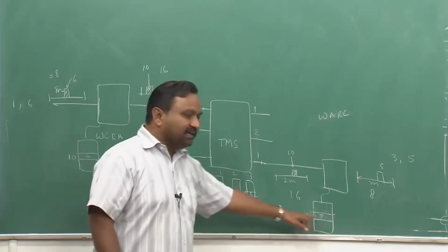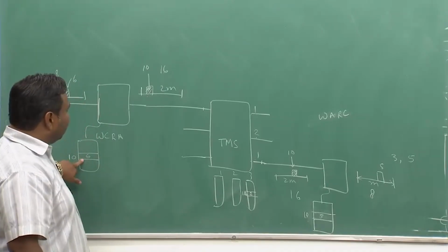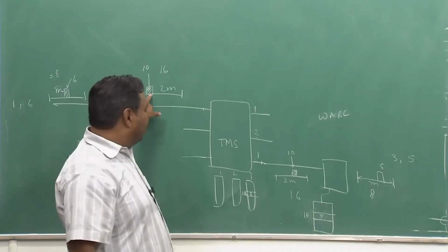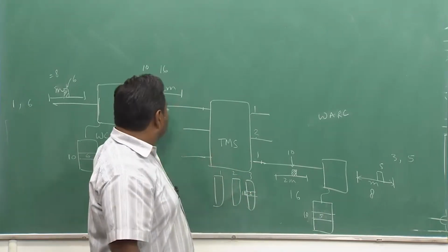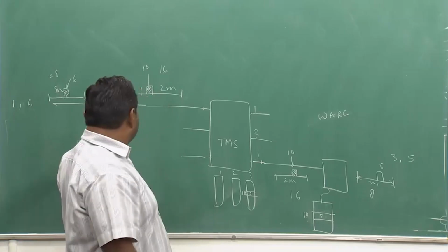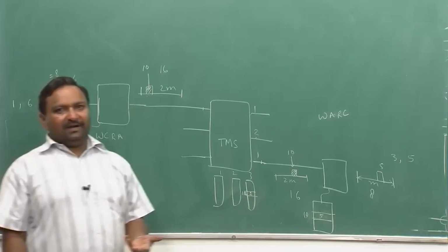the addresses in all the 3 control memories in all 3 stages. So, whatever is the input port comes here, whatever is the middle slot which I am using comes, whatever is the cross point will be used at the 10th slot, the middle slot will govern the memory location where the writing has to be done. It has become far more simpler to handle.